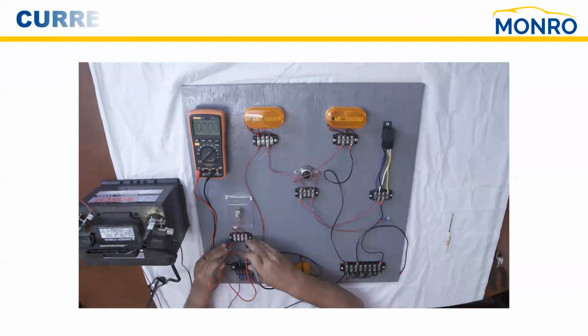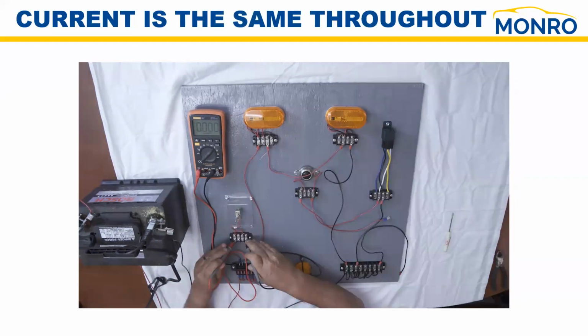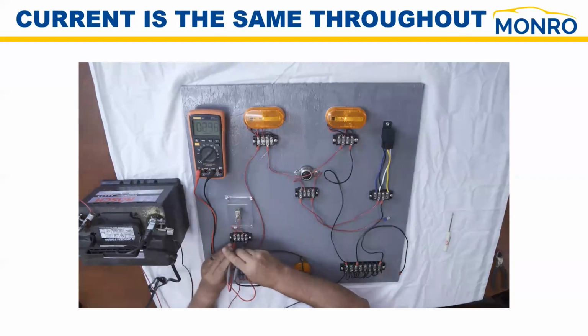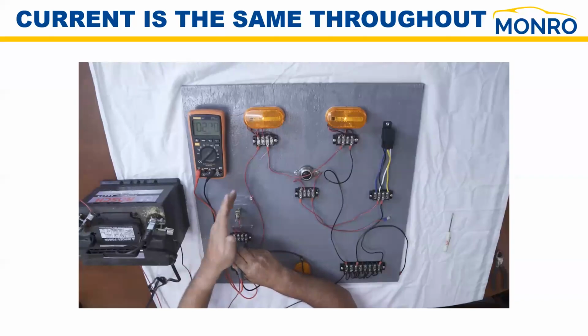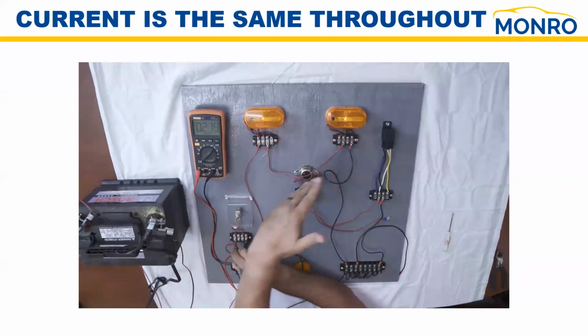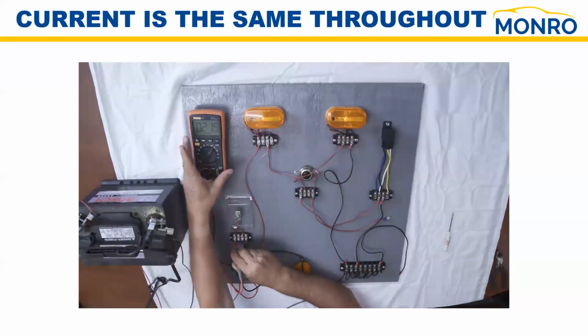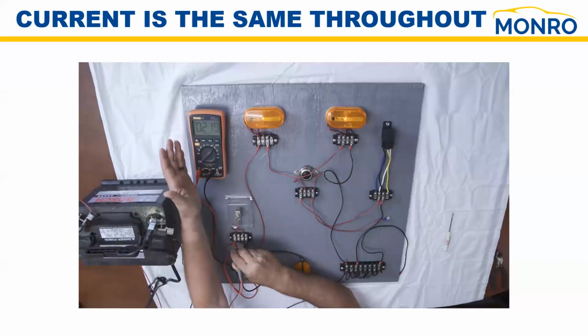Now, let's take a look at another place. Let's say this time we're going to measure the current coming through the switch. And we know the meter is working as soon as everything lit up. And guess what? The same 0.22 amps shows up that we had.